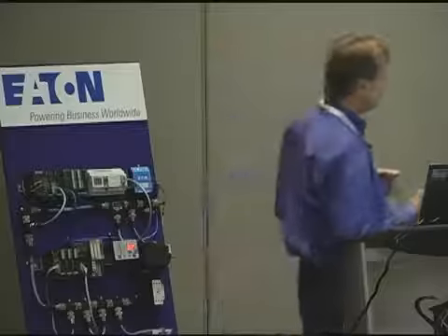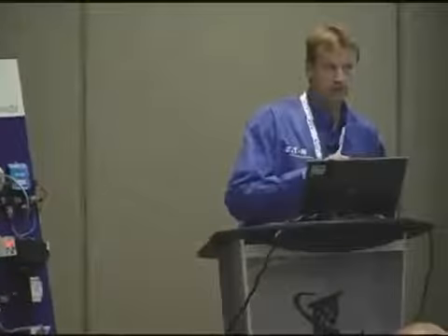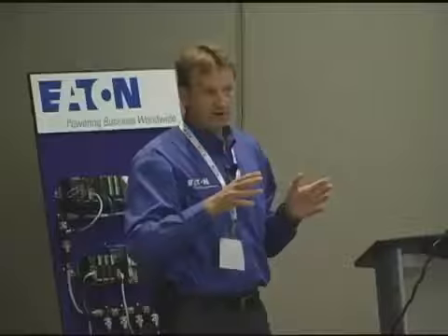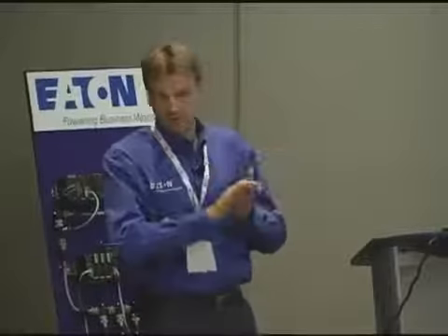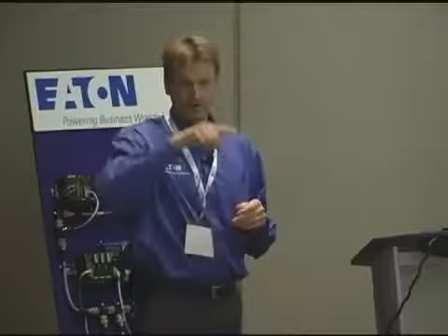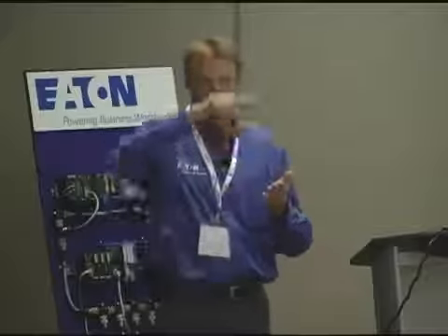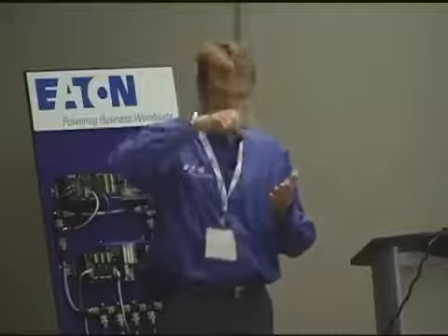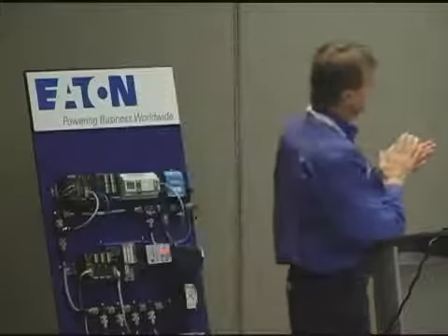What happens is if you have a lot of capacitance in a cable and you send a square wave, like you want to send a 1, so you're going to send a square wave down the line. With a lot of capacitance, it charges the cable. And when you get cable charging, you can get ringing on your line. So where you wanted a nice perfect square wave to be a 1, now you've got ringing going on because you're charging the cable and it discharges and charges. So now you got ringing on there. Plus, if you have a long network, that ringing can actually get reflected back.